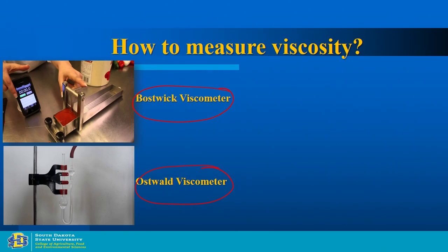Sometimes in product development, that's all they care about. One number, give me a number, life is good. If the number is less, I know it's low viscosity. Number is higher, higher viscosity, I don't care about characterization. But if you are a scientist, you want to make sure that you characterize your fluid first, make sure that it's a Newtonian fluid or non-Newtonian. Accordingly, you classify it. And it's very important that you do that if you are a scientist. If you are a product development person, no worries, you just measure one viscosity, life is good.